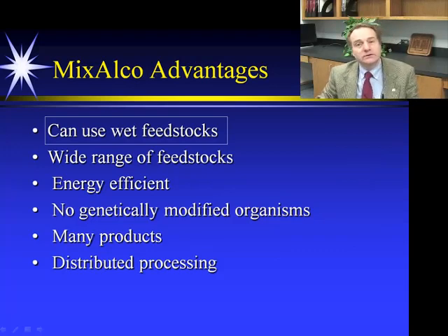Now, what are the advantages of our technology? First of all, we can use wet feedstocks. The advantage of that is when you harvest your biomass, you simply go into the field one time, chop the biomass, and put it into piles, and these piles can be stored for as much as a year without significant degradation. So it's a very inexpensive way of collecting and storing the biomass, provided that it's wet. If you have to dry it, then you have to worry about, is it going to rain during the harvest season, and when I stack up my bales, is it going to rain on them and damage the biomass?